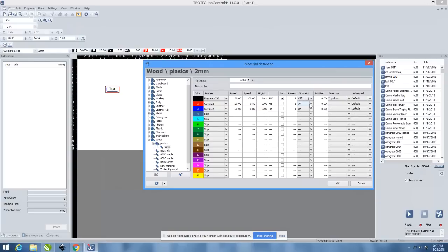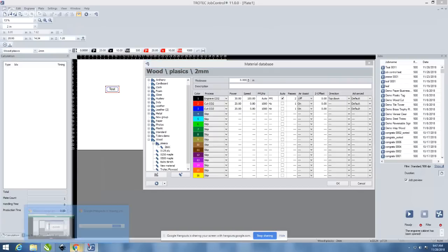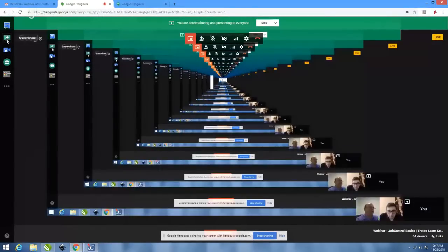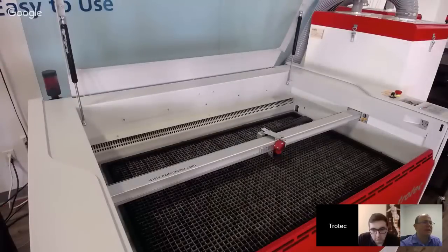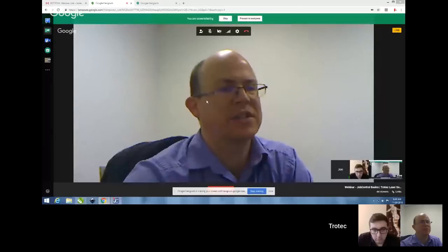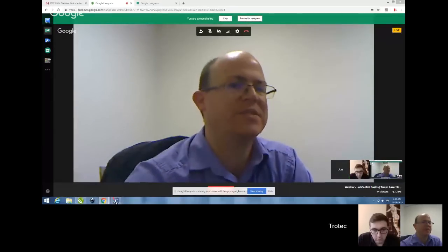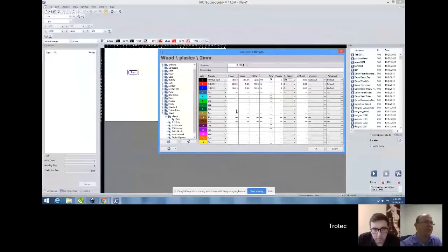So if you have the nozzle on the laser head on a Speedy 300 or a Speedy 400, the basic rule of thumb is if nozzle on, air must be on. If the nozzle is off, then it doesn't matter as much, but nozzle on, air must be on. If you try to have the nozzle on and no air, that nozzle will basically act almost like a scoop, and it can pull smoke up onto the lens and you can damage it. So it's very important that if you're running the nozzle, you have the air on to protect the lens.